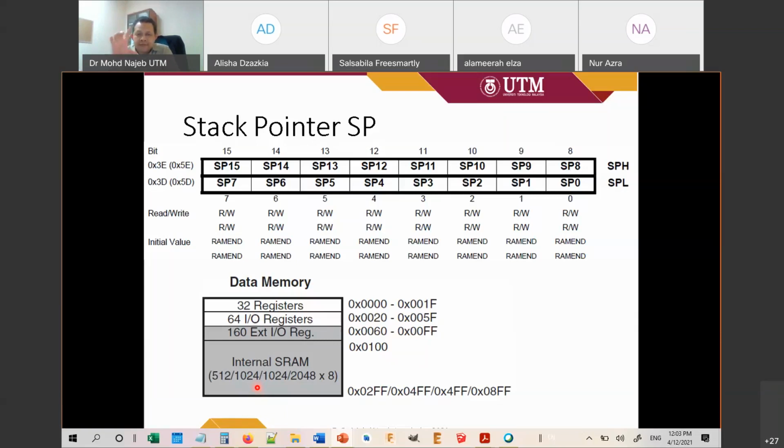Usually when you use them in the interrupt service routine, you don't store that much. You do some processes, and then you get a final value. Remember again the global interrupt in the status register: when you are servicing one interrupt, you cannot have another interrupt happening.